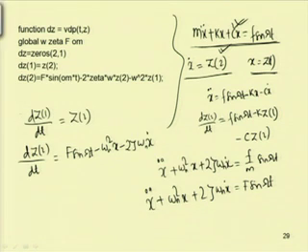So, by putting these two equations in a function, in MATLAB this function is written as VDP. Function dz equal to VDP, and using global variables, w represents omega n, zeta, f is the amplitude of the excitation, and om is the frequency of the excitation.